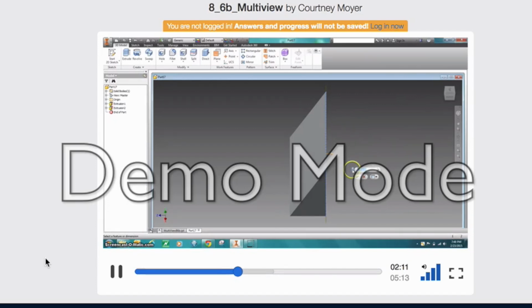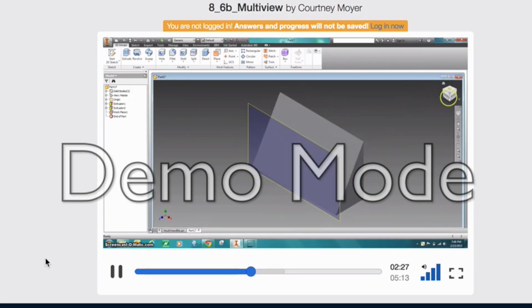and if I tell it to go an inch, you can see it kind of goes an inch away. But I want it on this part. So I'm going to type in there -1 inch. And that puts that plane. Now, if you think of a plane, kind of like a glass plane, like a big sheet of glass in front of that. So that's what I need.